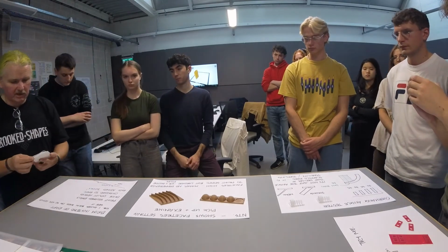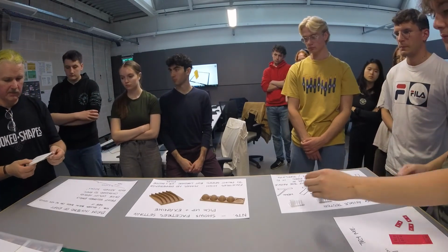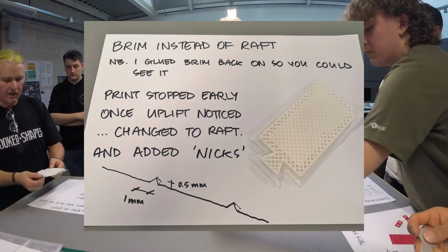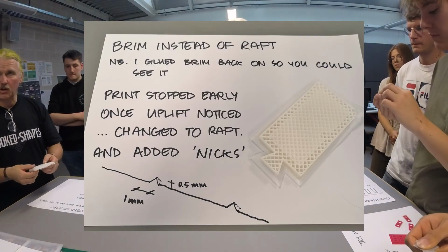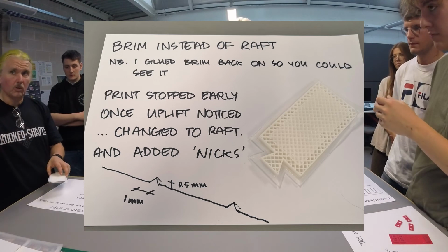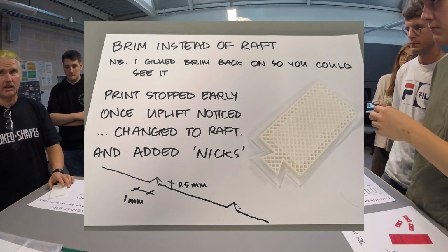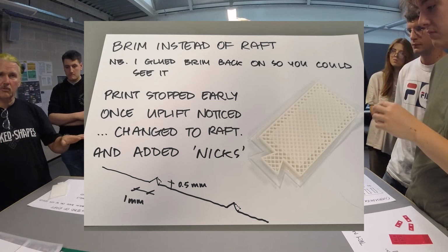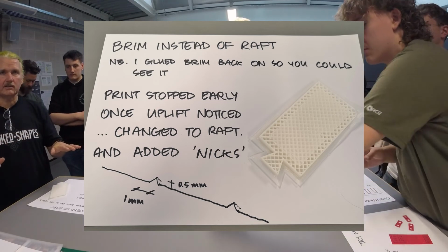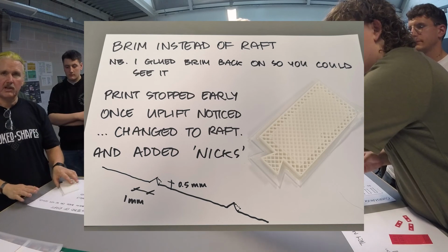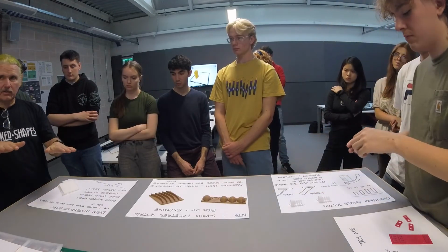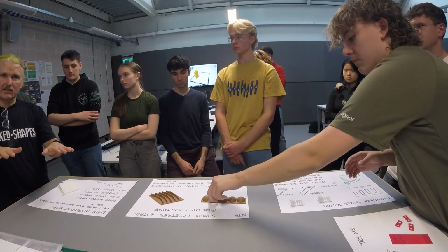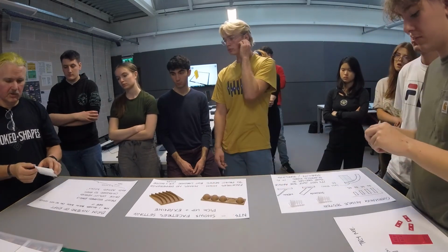And then the last one here, the brim one. This is the choice of the guys in the Make Lab. This is what they will generally use instead of the raft, which takes a lot longer to create because it goes under the whole object, 4 layers thick. But the benefit is that the top of the raft is absolutely flat, whereas the brim is so thin. If the deck of the printer isn't absolutely level, the brim isn't level either. It's so thin, it comes through with it.